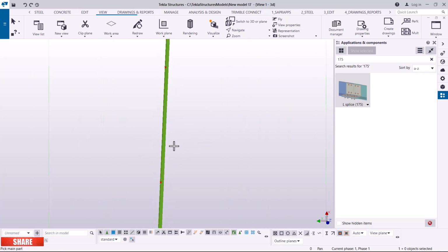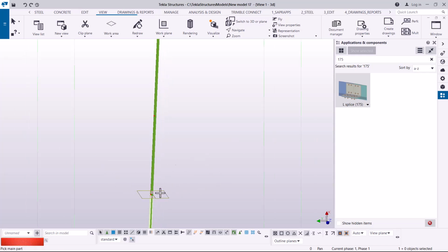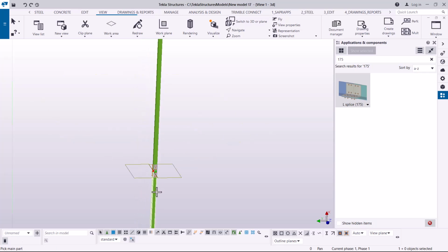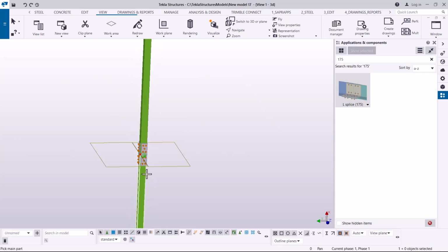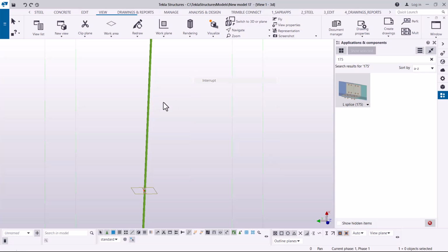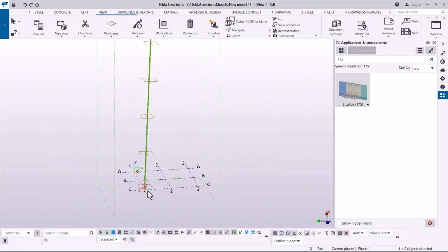So this stretch all the way upward, the leg sizes are the same. Then from 30 meters high is when the legs will start to change. So let me just create connections there until we get to that spot. This is how we go about it, and I would like you to try that by yourself.